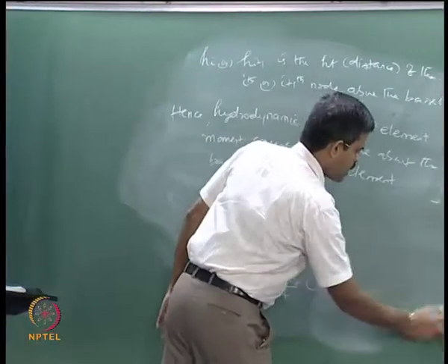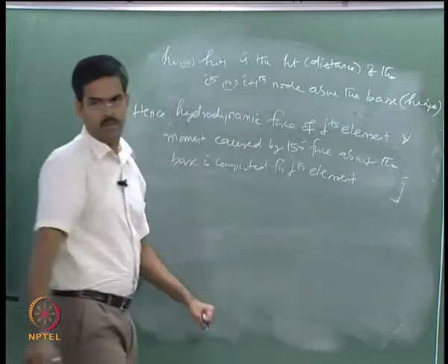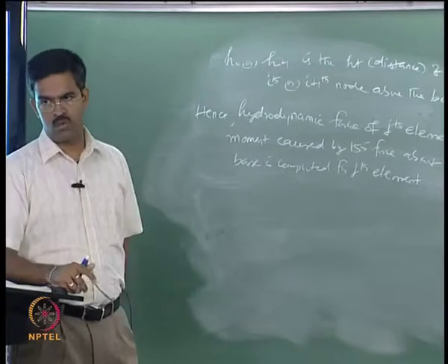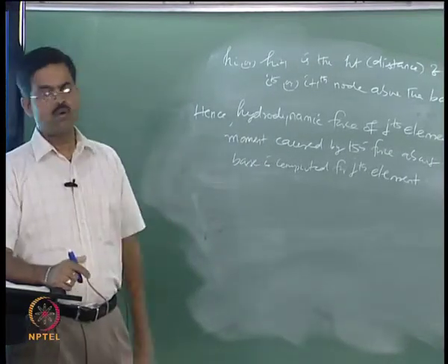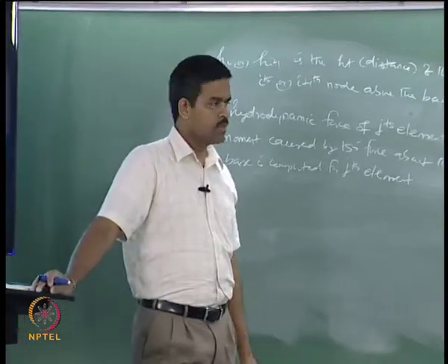So, now my f of t comprising wave and wind is clearly known to me. I know how to divide them into segments, the superstructure part above the still water level, find the aerodynamic forces and the corresponding moments of these forces about the base of the tower.